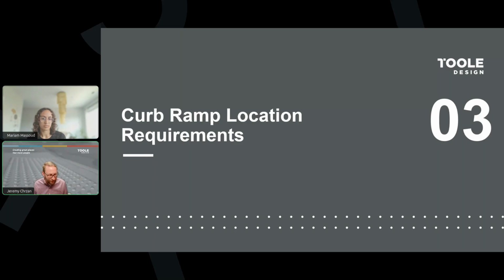I've also had projects, though not in Ohio, where I approached the property owner, identified that some minor grading within their property is needed in order to construct a fully compliant curb ramp. Would they be willing to sign this letter format, allowing me to disturb a little bit in their property and reseed it and return it to a condition similar to its existing condition?